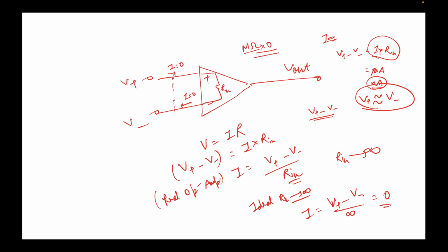So whatever voltage is being reflected here, you can simply reflect it here. Note that this is not the comparator circuit. We're not talking about comparator circuits here. In comparator circuits, we compare these two values. That's a different case. But if you have some negative feedback RF and some resistor R1 here, then you can assume that whatever voltage is here, due to the virtual short, that voltage is being reflected here, due to Ohm's law across this resistor. That's what I meant by virtual short.